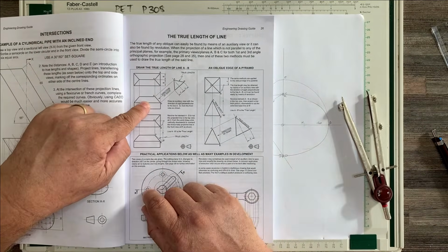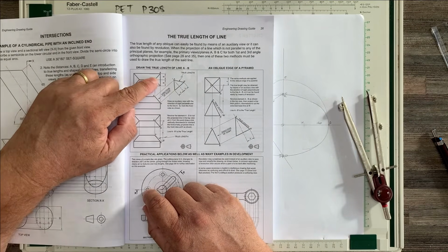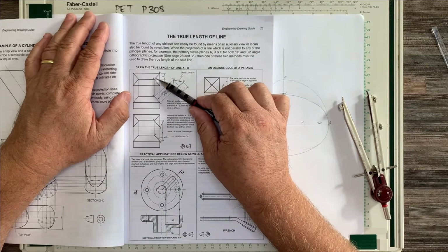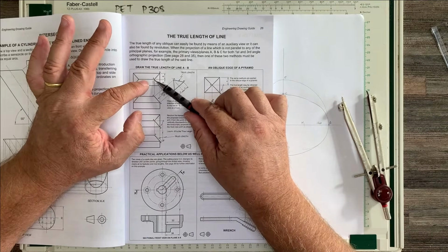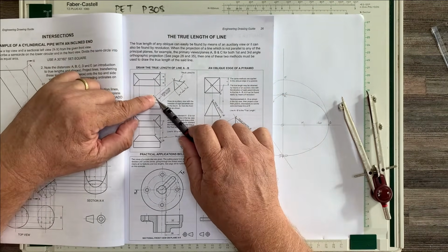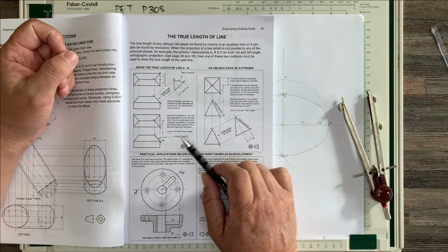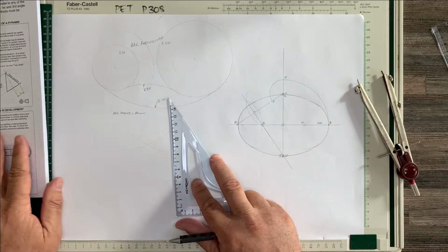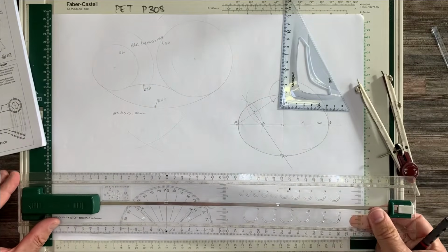So for example, this house has a pitched roof in both directions. So line AB going in that direction there, from the top view, it's sloping downwards, so it's longer than that distance. From the side view, it's sloping away from us, that's longer than that as well. So we have to find that true length. So if I had to do a quick construction,